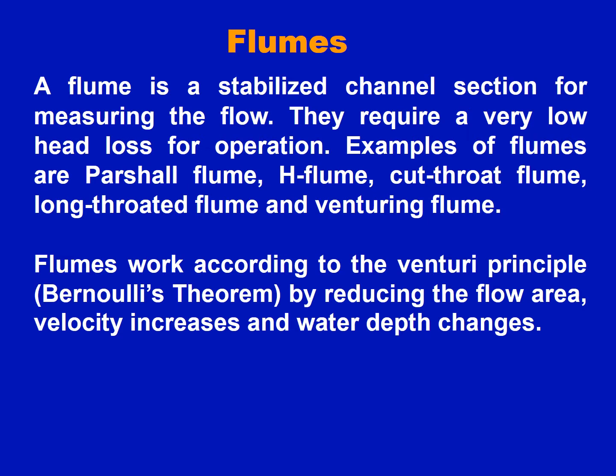These flumes work according to the principle of the venturi meter. Most flumes have a shape similar to the venturi meter. Venturi meter, if you recollect, works on the principle of Bernoulli's theorem. What is the statement of Bernoulli's theorem? The sum of pressure head, velocity head and potential head is constant.